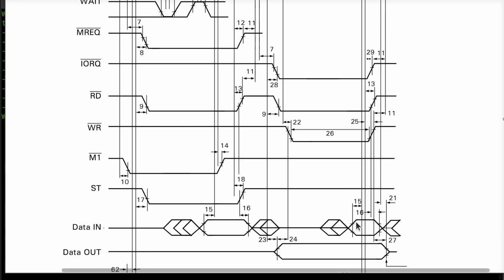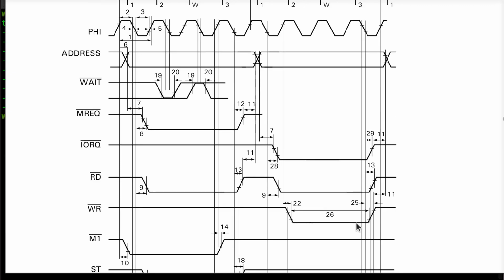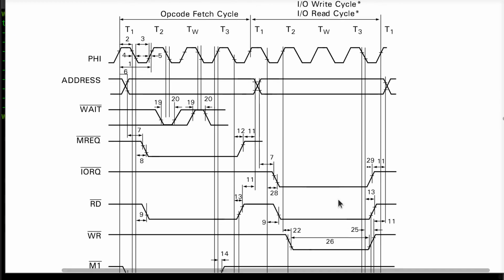Okay, if you look in the spec, these little plus marks are like 80% or 70% of the way to where it's got to go. Okay, it's not over here. It's done slewing to its voltage. Okay, is the way I want to think about it. So that's the worst case scenario. In my mind, in other words, I'm moving this all the way out to here. Okay, making sure that I'm ready so early that I can't have a problem. Okay, so that's how you want to think about when the CPU reads from the FPGA.